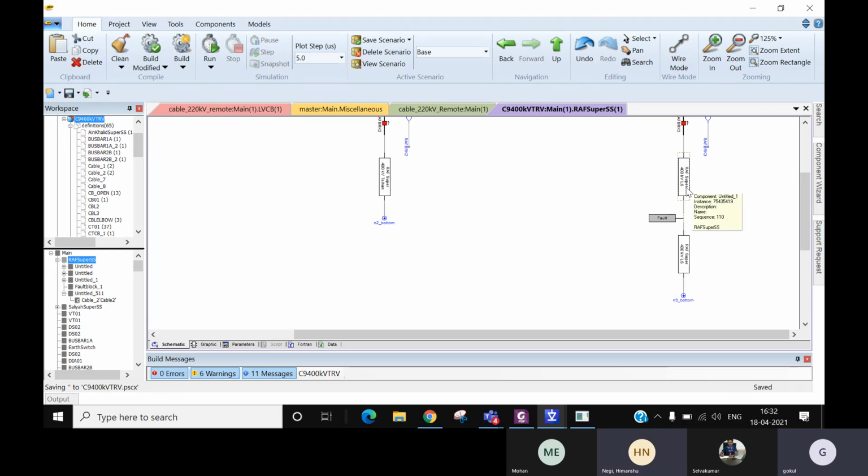Is there any logic for what short length means of the full route, or can you just randomly select a value close to the substation of interest? That will generally be 30 percent. If you have 30% of total route length, yes, generally 30%. So this is short line fault.